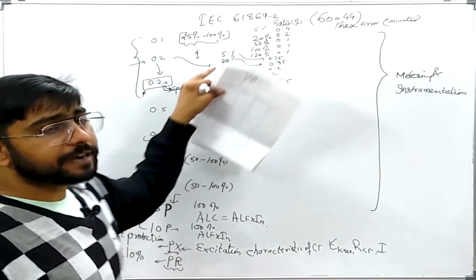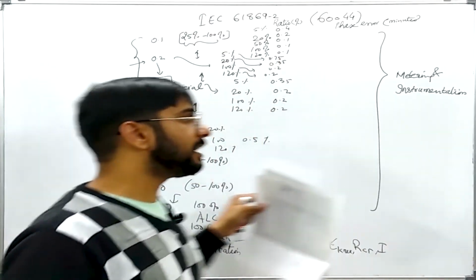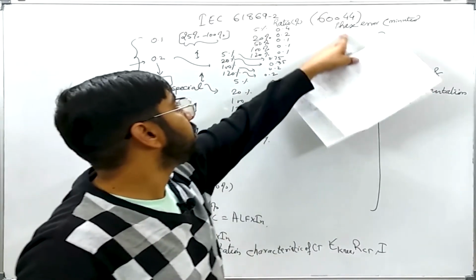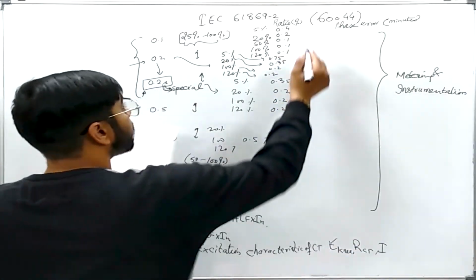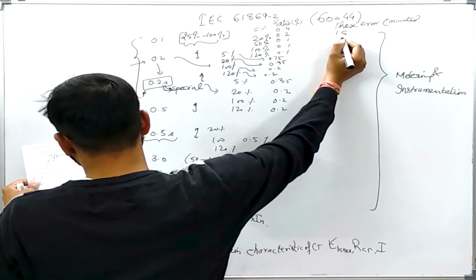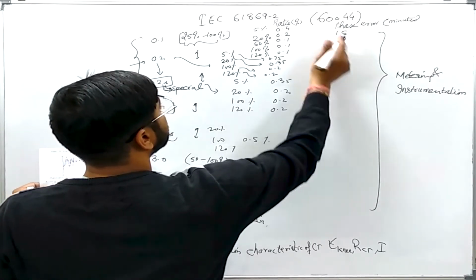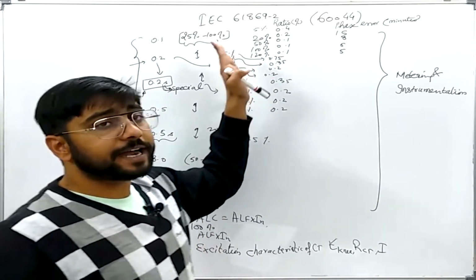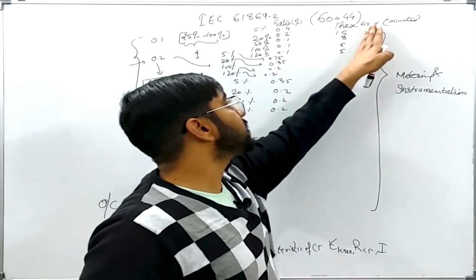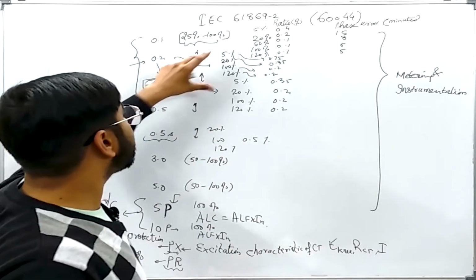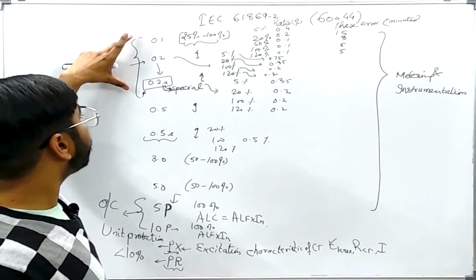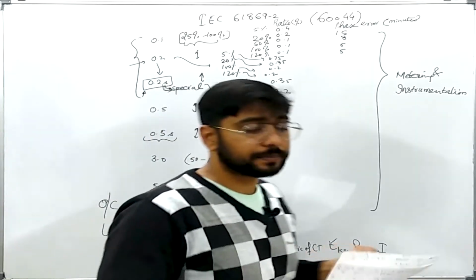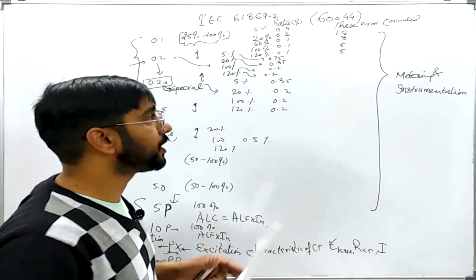In this way we can find the table in the IEC and we can find the specification for the ratio error and the phase angle error. The phase angle error will be 15 minutes, 8 minutes, 5 minutes, 5 minutes for these value of currents. Okay, so in this way we can find the ratio error and the phase error of a CT at a given current for the various kinds of classification of the CTs. Okay, so this is the classification.